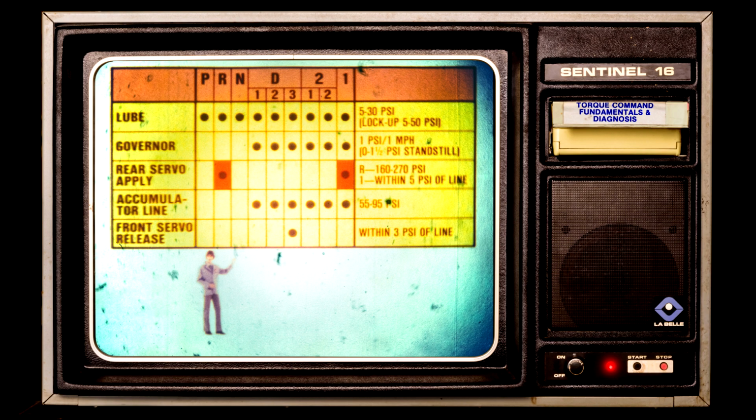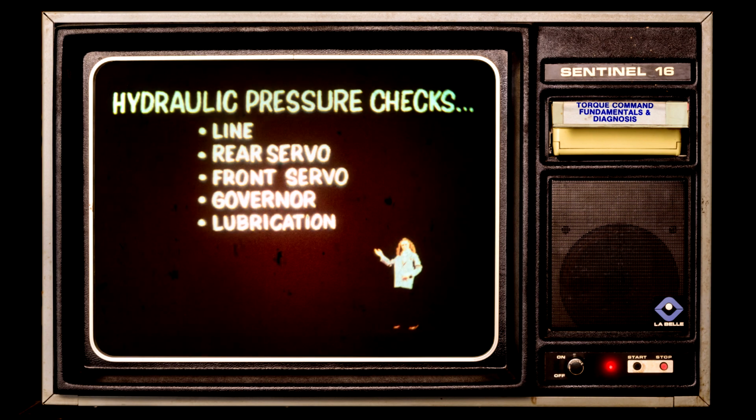For a second example, let's assume that low pressure is noted in reverse and manual first. What's the cause? Rear servo leakage should be suspected. This kind of leakage could prevent the rear band from fully applying.